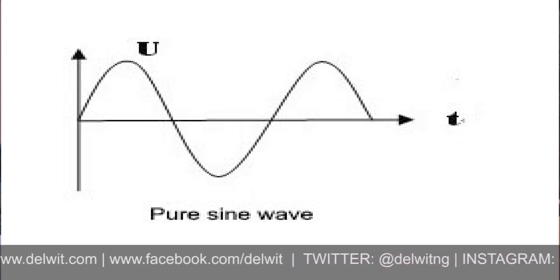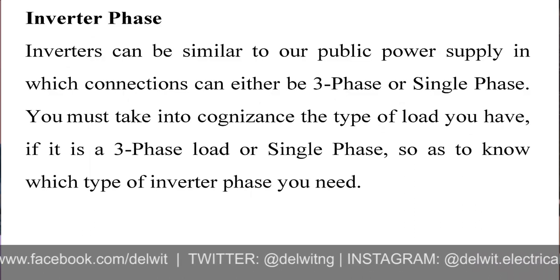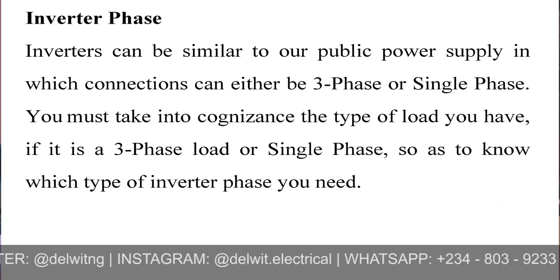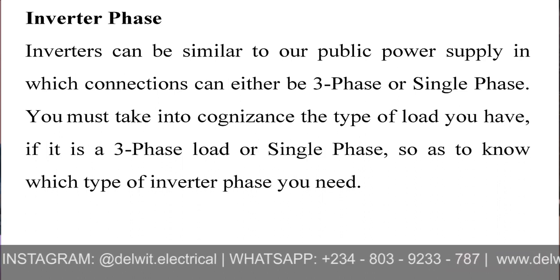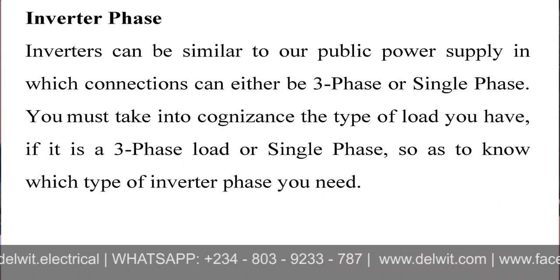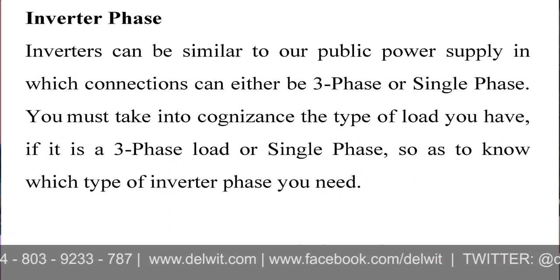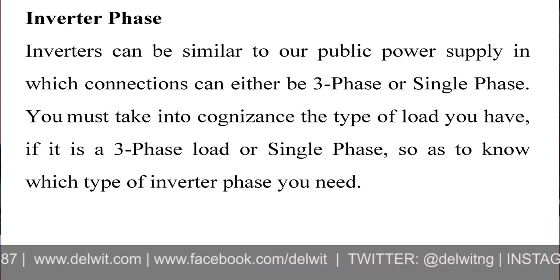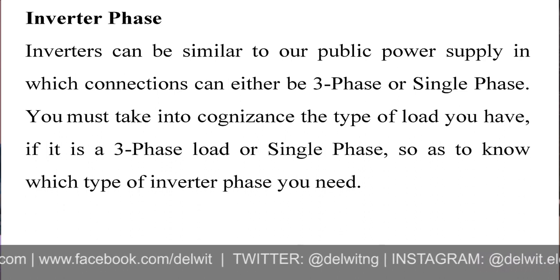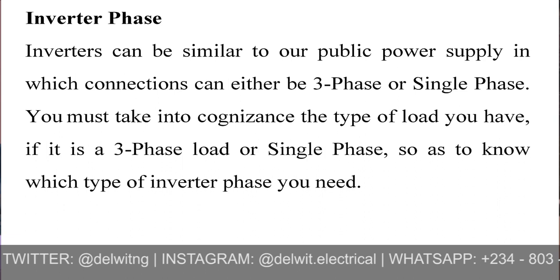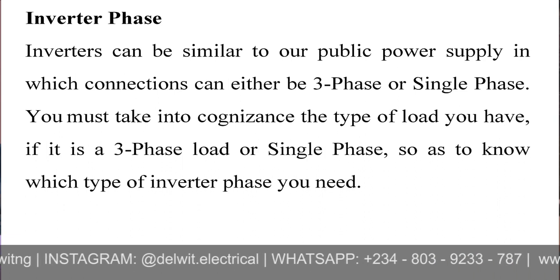Then the last one we're talking about is the phase. We have single phase and we have three phase. Depending on your kind of load, that will determine the type of inverter. If all the load in your house is single phase, why spend the resources to buy a three-phase inverter? Three-phase inverters are usually more expensive than single phase. But if you have three-phase equipment, it's advisable you buy a three-phase inverter.